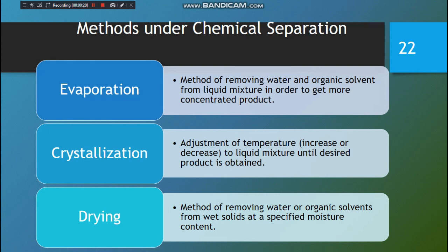Evaporation refers to the removal of a relatively large amount of water from a material. In evaporation, the water is removed as vapor at its boiling point, and the vapor from a boiling liquid solution is removed and a more concentrated solution remains. In the majority of cases, evaporation refers to the removal of water from an aqueous solution.